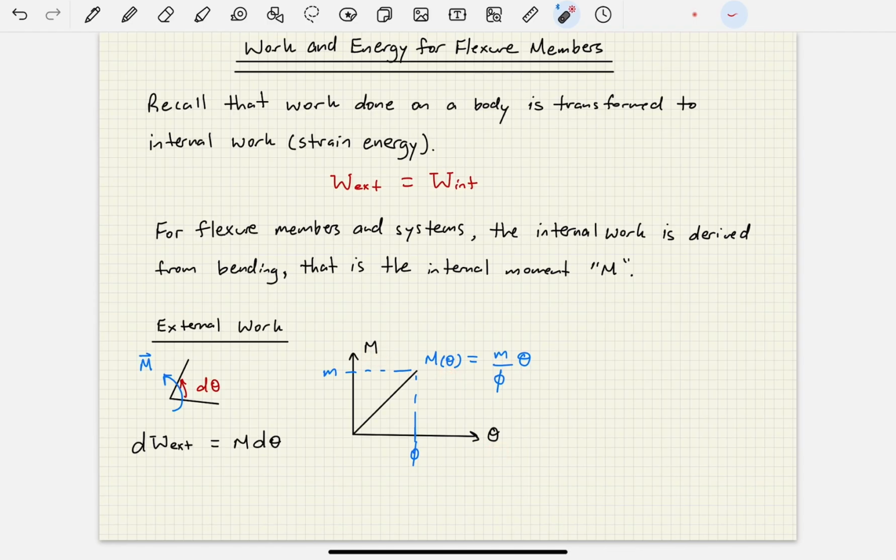Have we seen something like this before? Yeah, definitely. We saw something like this in a previous video, but with a force directed along a line, okay? Now, what I can do is perform some integration and find the area beneath this curve or beneath this linear segment, and that will get me this external work. So really, I'm just integrating both sides of this equation.